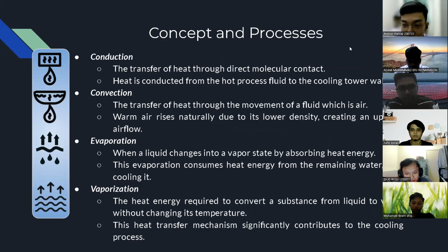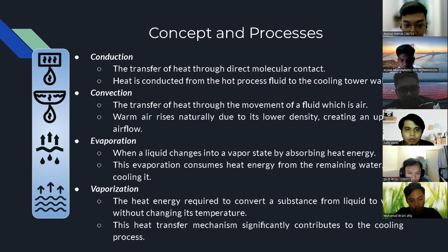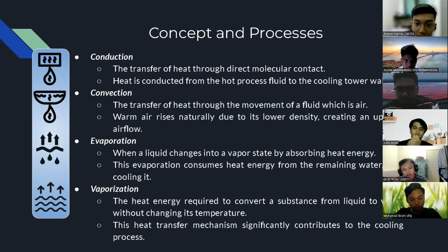Okay, how the cooling tower works. First the hot water enters the tower, and the hot water will spread over the material that is called fill. Fill media will increase the surface area of the hot water to allow the cooling process rapidly. So after the cooling process has succeeded, the cool water will be collected at the bottom, and the cool water is returned to